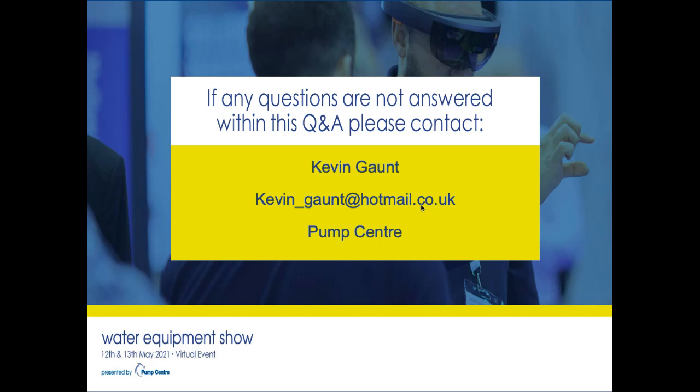Perhaps we should make sure that the pumps will run. This is often found with valves that are not required to operate very often. They sit there, and will they operate when they're required? Well, unless they've been exercised, they won't. So there's a question within that question. If something is really critical, perhaps people ought to be visiting the installation and undertaking some sort of checks on it. That would be my answer.